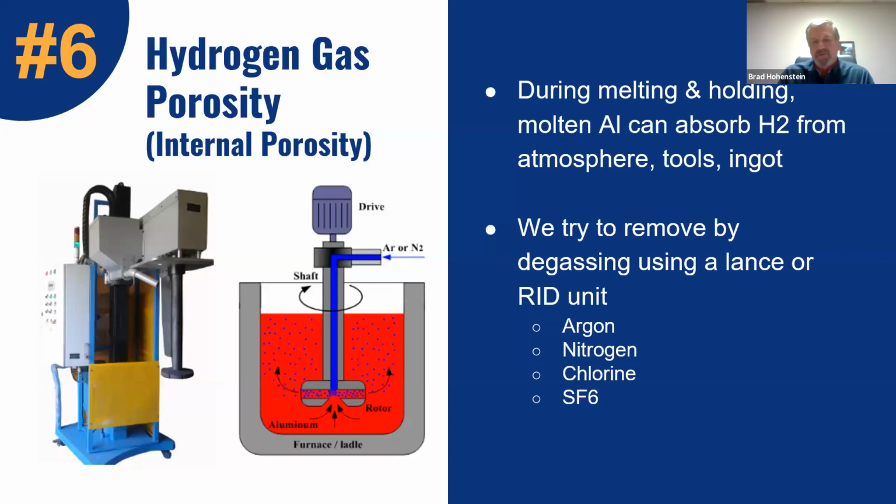If the criteria is a good surface finish, then the internal doesn't matter, right? The hydrogen porosity is never on the surface, and shrink typically is. So if you want to eliminate your shrink, or you have a corner that needs to be good where you don't need shrink in the corner of the casting, sometimes a gas level is okay. It's pretty much a standard practice in permanent mold, depending on certain parts, to add some gas in some form or another. I've seen potatoes, I've seen 2x4s, I've seen pretty much everything used to add a little gas into the part. And some customers will state it right on the drawing what they want. Yeah, and I think it goes back to the testing too.